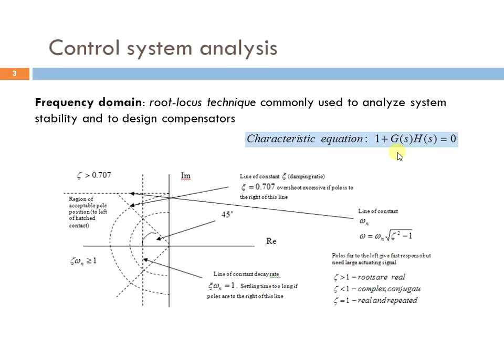Now on the s-plane, we have already discussed that the requirement for closed loop stability is that all closed loop poles lie on the left half plane of the s-plane. Further, the precise locations of the closed loop poles determine such parameters as the damping factor and the undamped frequency of oscillation, and thus also dictate the transient response characteristics of the system.